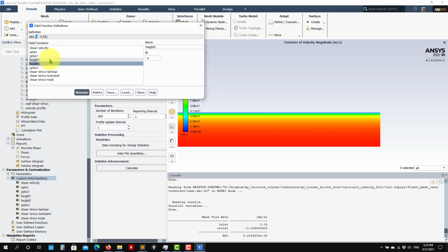So then, for instance, shear velocity. I know that shear velocity is the square root of wall shear divided by density. So you compute that quantity. Then, for instance, the y plus 2 is equal to density times height. Height 2 is the one that is the right one. No, at that point where I'm going to plot this y plus, it is 0, okay, times shear velocity. So this is the shear velocity, okay.